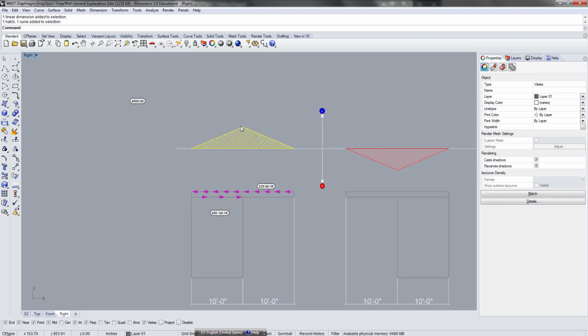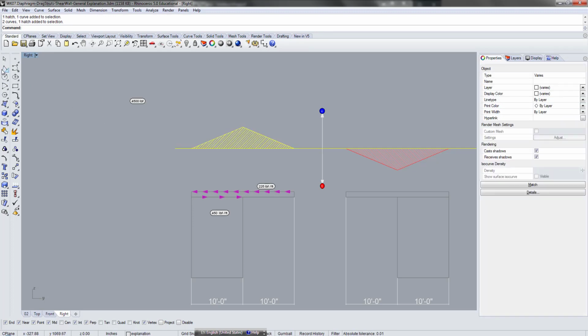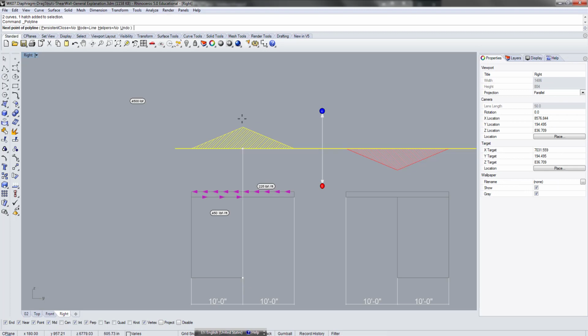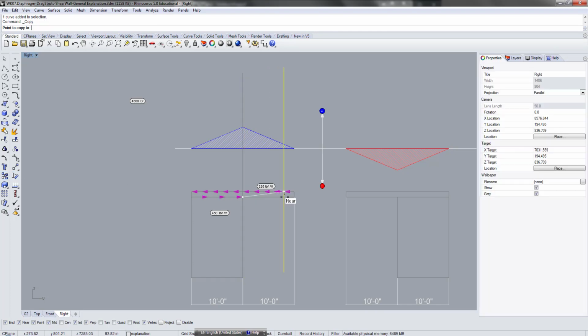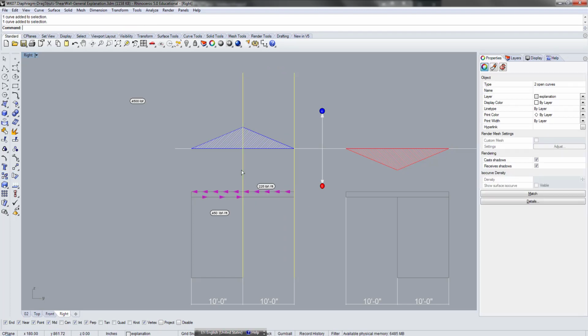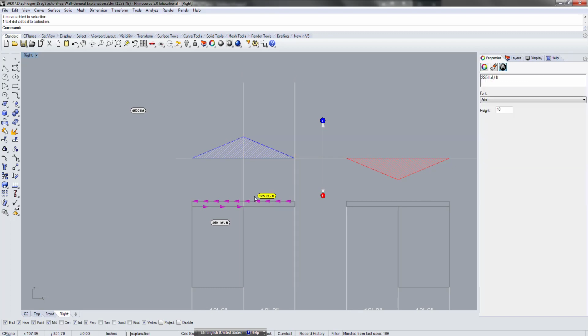So again, if I draw 225, it's going to be too large. But right now, between here and here, in this zone, the only thing that this beam is experiencing is this compressive force from the floor above, 225 pounds per foot.